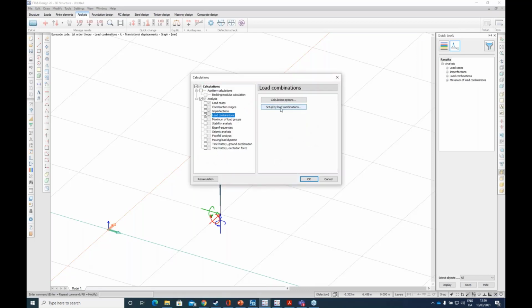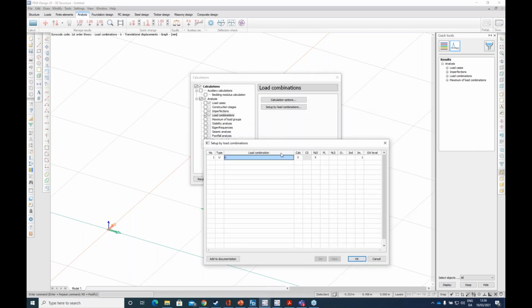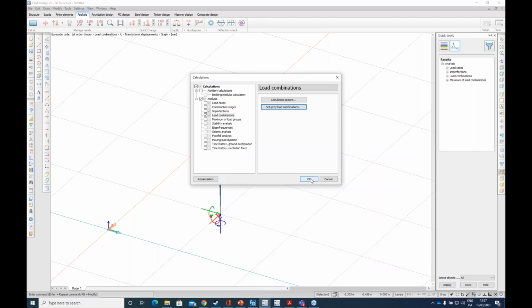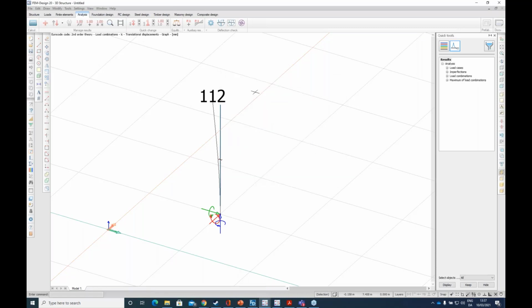Having that calculation, I can, as I saw here, choose a type of calculation, which is second order analysis. Tick that box and then choose one of the imperfection shapes that I want to look at from my previous analysis, which is basically a stability analysis with the imperfections. So we'll do that second order analysis based on those, taking into account those imperfections.